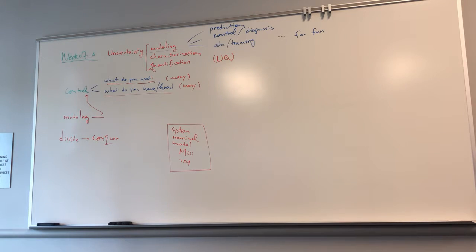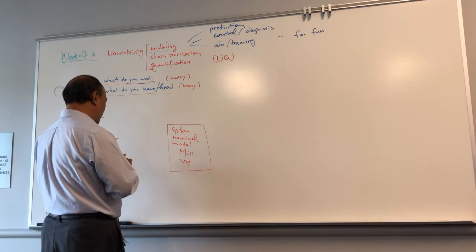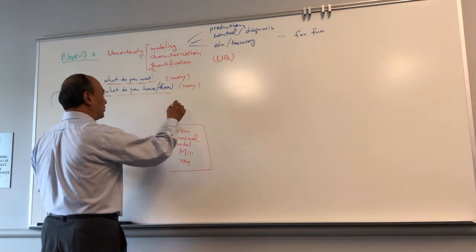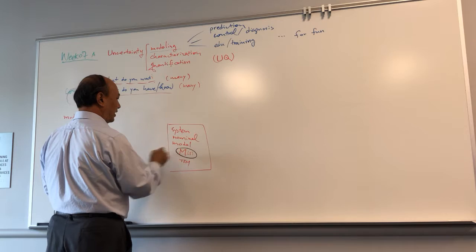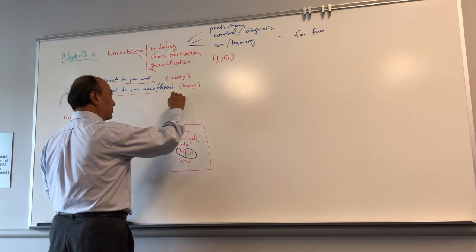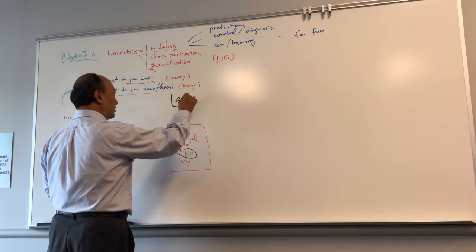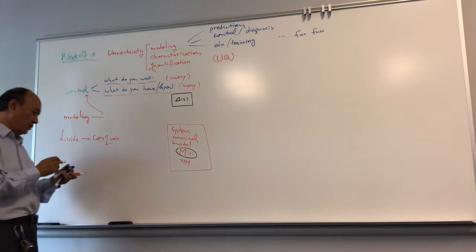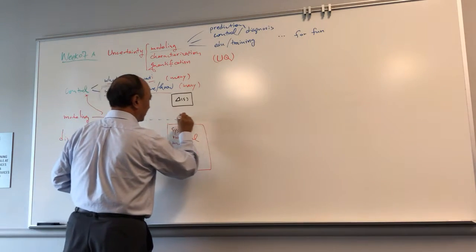The key idea of robust control, starting from this chapter, is that we assume we can divide the system into two parts. One is called M(s), the nominal. Another one is called Delta(s). This is called uncertainty. So we draw a line between them.